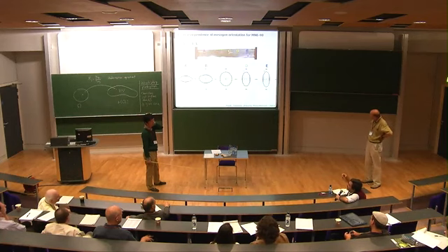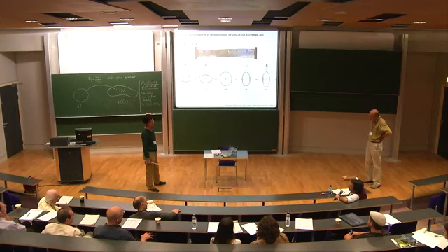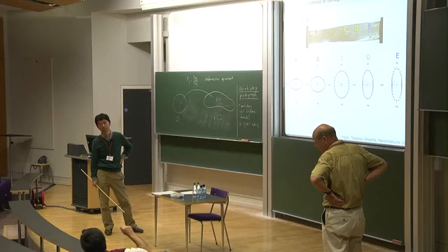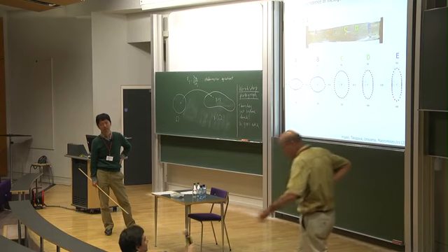So I often get asked the question about similarities with respect to wrinkling in thin sheets under tension. In that experiment, wrinkling is a compressional instability that starts because when you stretch close to the clamps, you generate compression and oscillations out of the plane, of the kind that Peter was mentioning. And this phenomenon is very thickness dependent somehow. So since you also get thickness dependence, I was wondering whether this could be a hint for your experiments as well.